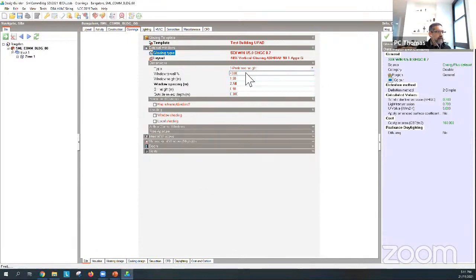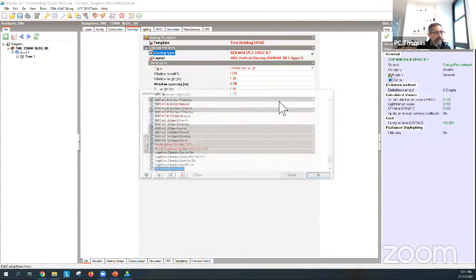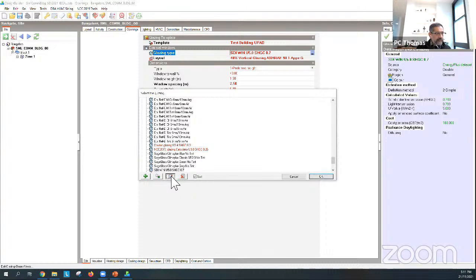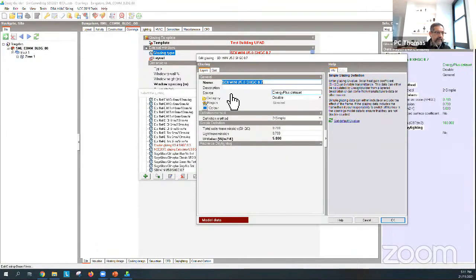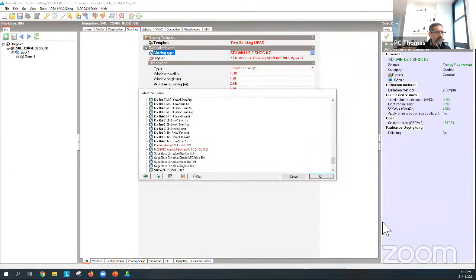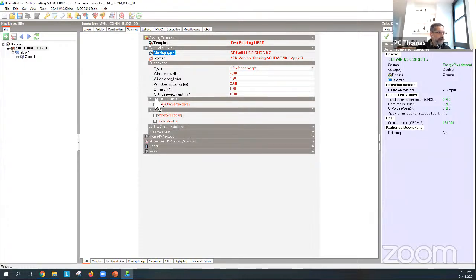The only thing to remember is that there is a difference between just the glass data and the glass plus frame data, right? And when you put the numbers in here and you remove the frame and dividers, then we're really talking about the whole window's performance. See, I've removed the frame and divider value here.